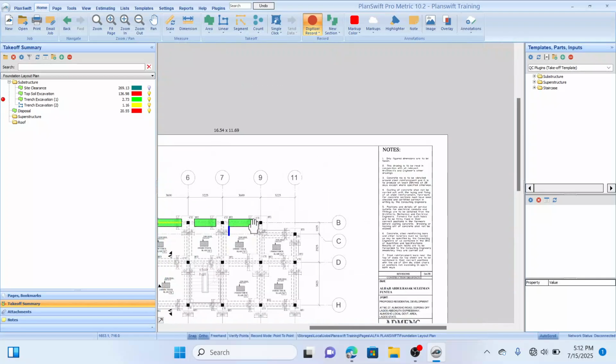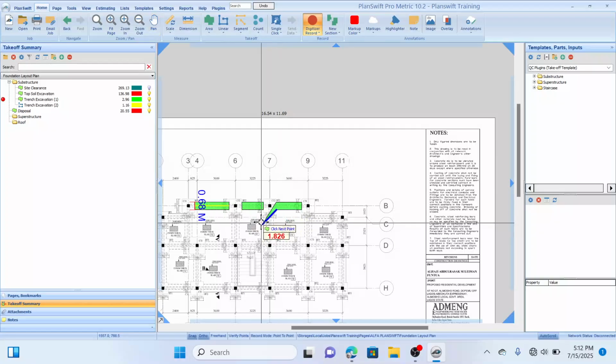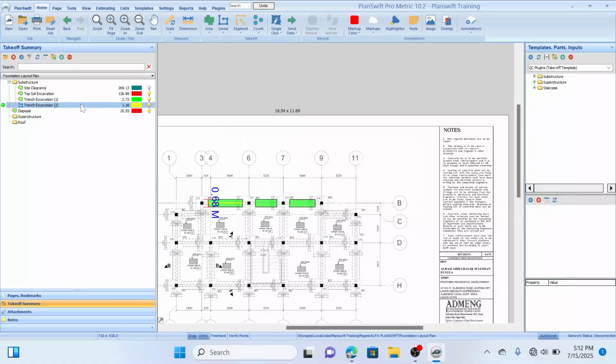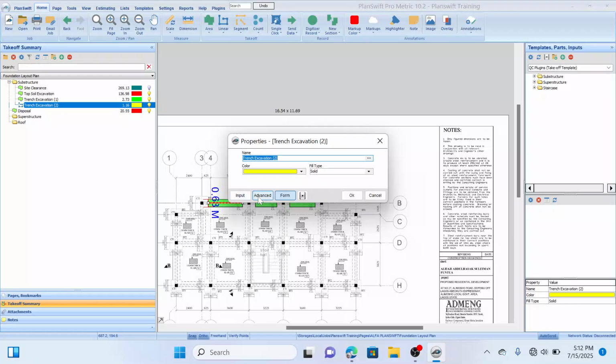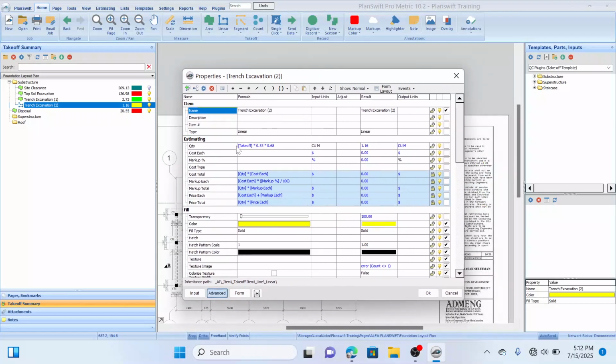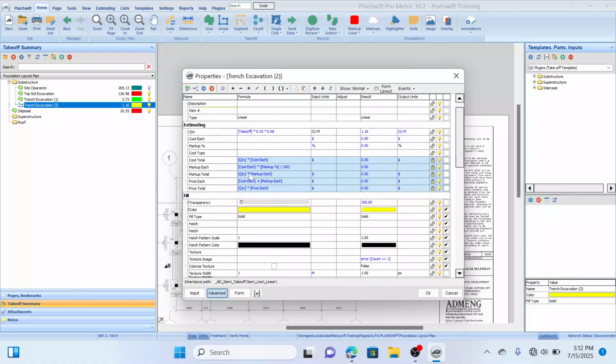So let's end the measurement here. I want to show you guys something else. So I'll click on escape. The other tool we use here, which is our linear tool, I can also configure this tool to appear as an area tool. So to do that, what you need to do is that you double click on that tool, then you click on advance. If you check through what we have here under, where is it?